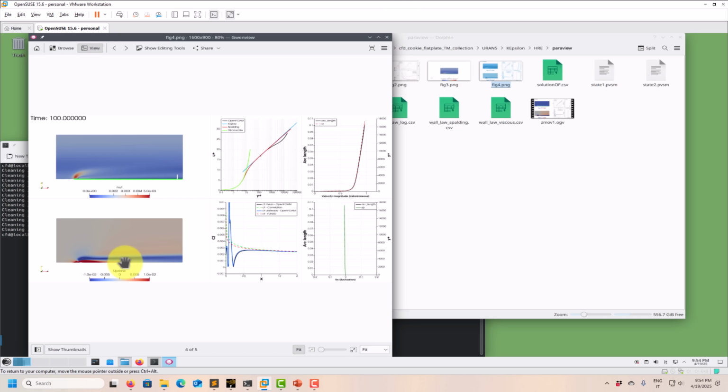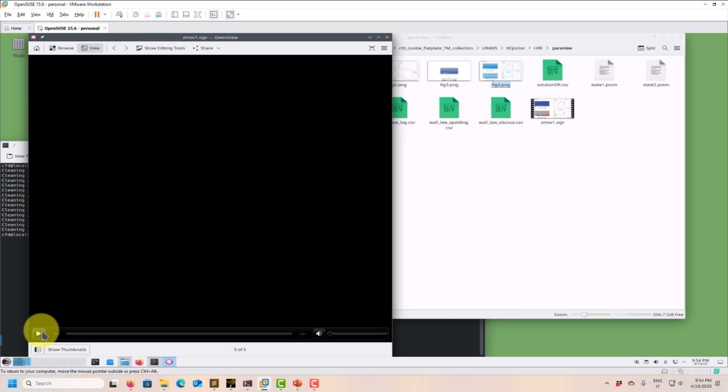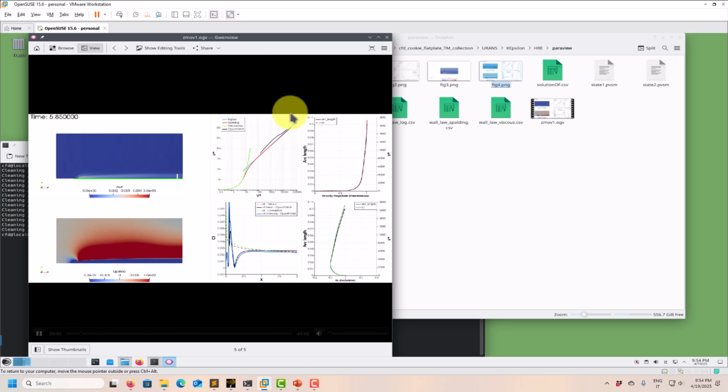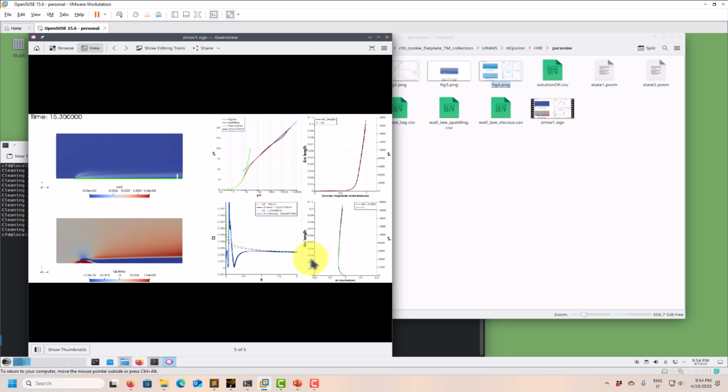And now here we have the effect of different turbulence models, okay? Wall modeling with K-Epsilon is completely smearing your fluctuations. You don't see anything there. So let me move here, and we have the movie. Let's take a look at the movie, because this, I think, is what we call interesting. Look at that, it's evolving here, moving in time. It will fit your theoretical value. This velocity profile makes sense.